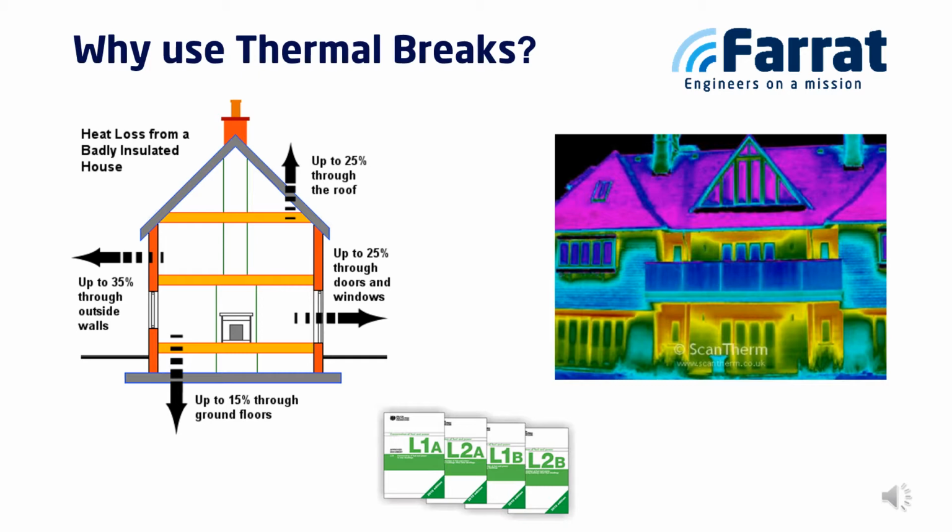Building regulations typically guide the designer in understanding the minimum requirements in thermal performance of building elements to achieve satisfactory thermal performance in respect of energy loss or gain. In England and Wales, Approved Document L gives detailed guidelines for calculating the target emission rates and target fabric energy efficiency rates and the minimum values to satisfy both of these requirements.